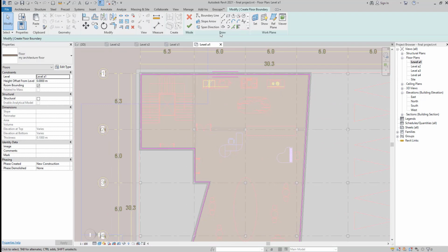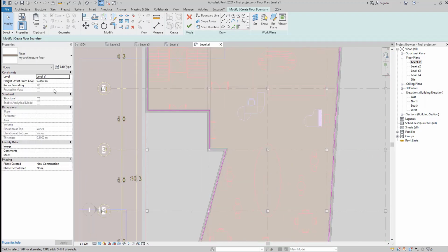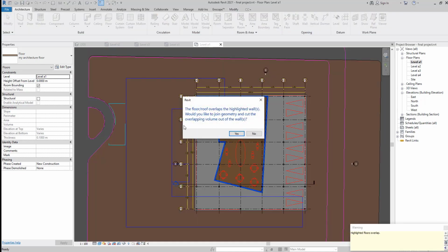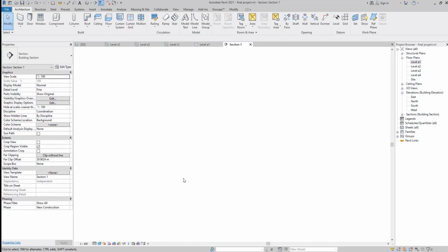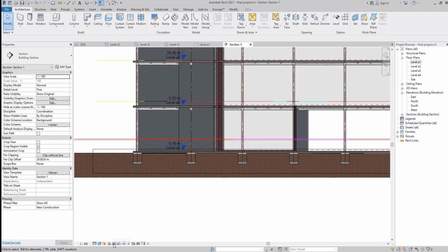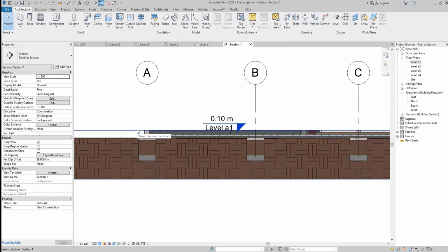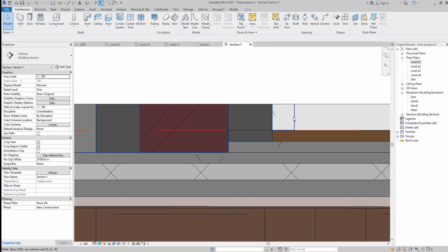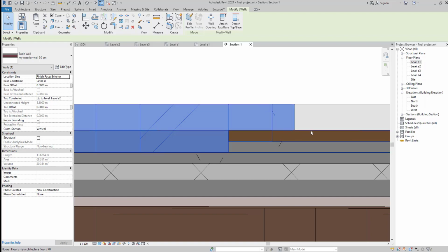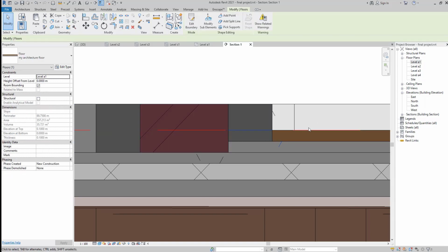And easily you just need to use pick wall. Every wall will be selected, and we are in a level. Everything looks fine. Our wall thickness is 1 meter. Our level is 1 meter above the structure level, and we just click OK. And we will say no right now, and we can go to the section, check them out just by clicking, and use this one. Here we go. So here it's our wall, as we will see, and here it's our floor.